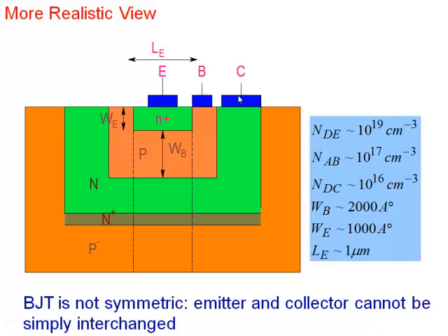Also note some other points about this transistor here. The emitter is heavily doped, and that's why we denote it by writing plus here, N plus. Heavy doping. Look at the doping here. It's just a typical value. Doping can be larger or smaller. Typically, it can be larger than this. 10 to the power 19 per centimeter cube. So it's a heavily doped region here.